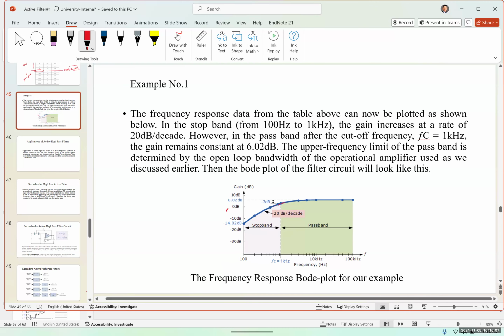It has a cutoff frequency, but the stop band has a very smooth angle, and it decreases 20 dB per decade, so it's not a lot of decrease. If we need a sharper filter that looks like this and filters any unexpected frequencies, then we need a higher order filter.